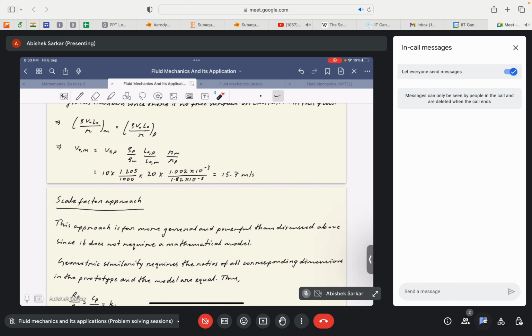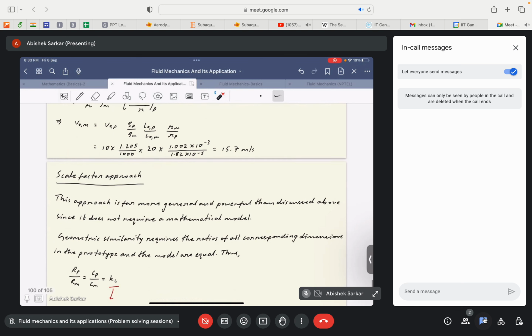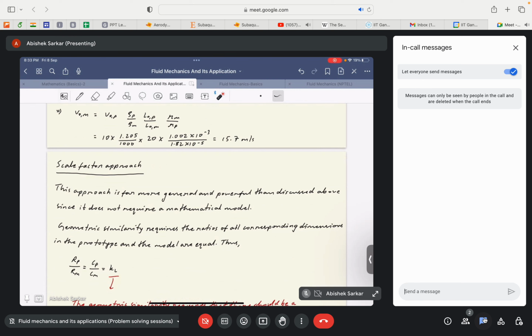It's actually a very difficult thing to achieve, even in very highly advanced wind tunnels. So reaching 200 meters per second is very difficult. That's why, to handle that discrepancy, the researchers find it ideal to change the fluid for the experiment so that this discrepancy in the velocities can be handled. Okay, so this is one of the approaches that we discussed. There are two more approaches that we'll discuss today.